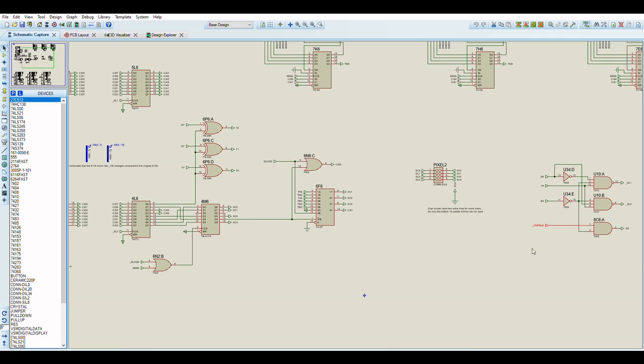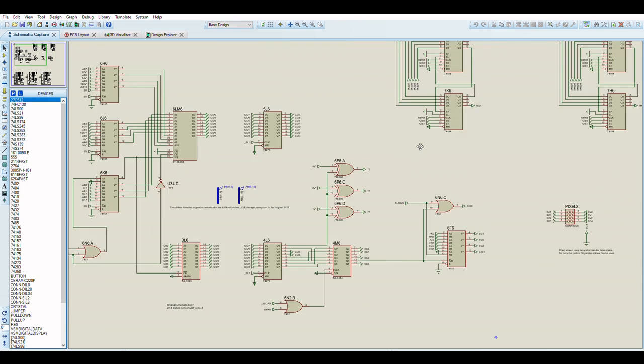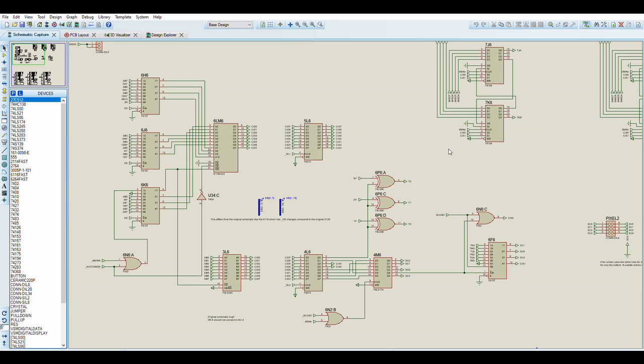And again, it uses the input for comp block and the horizontal pixel position, and it just switches these here. So you're reading RAM at the correct times, depending on horizontal clocked pixel position, and then latching it, and then using these values later on. This is just straight a latched character index. This is the latched color for the character.